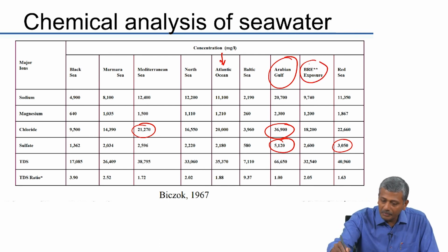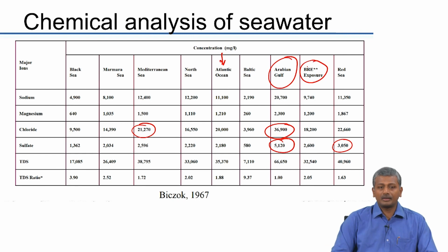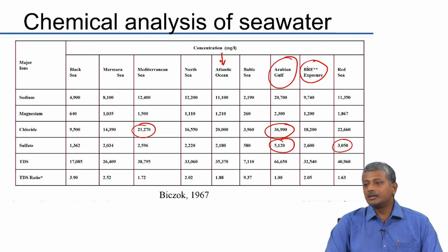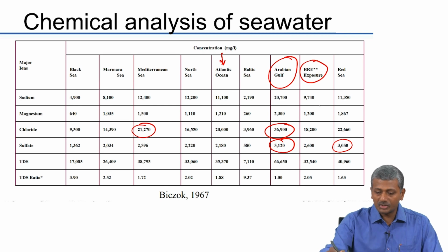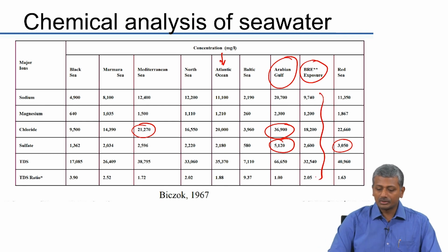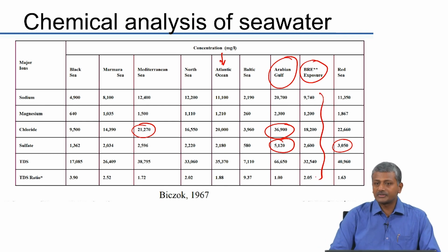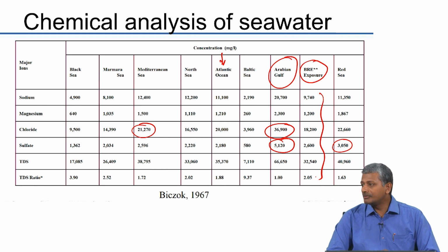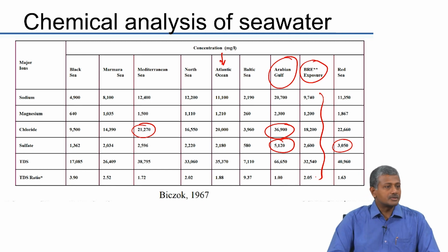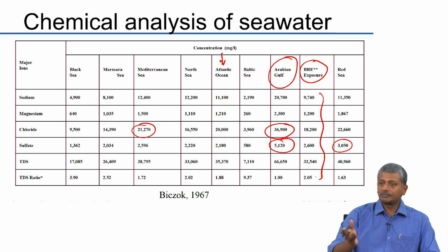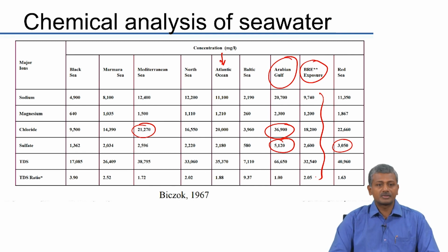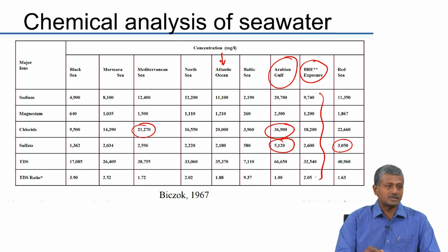Now, the British Research Establishment, BRE, created simulated seawater exposure conditions which had this concentration of the ionic species present in the water, and a lot of the current standards across the world which give you stipulations of water cement ratio, binder content and grade of concrete prescribed for marine exposure conditions, a lot of those values actually arose from the research done at the BRE.